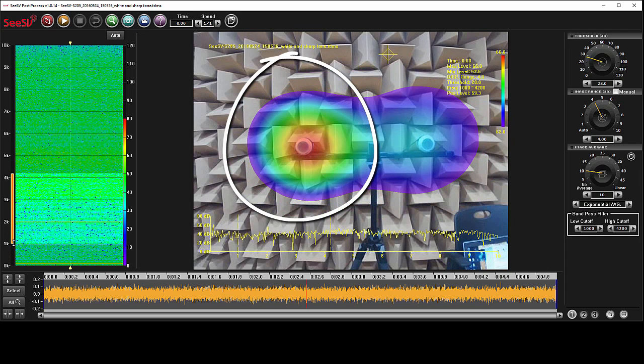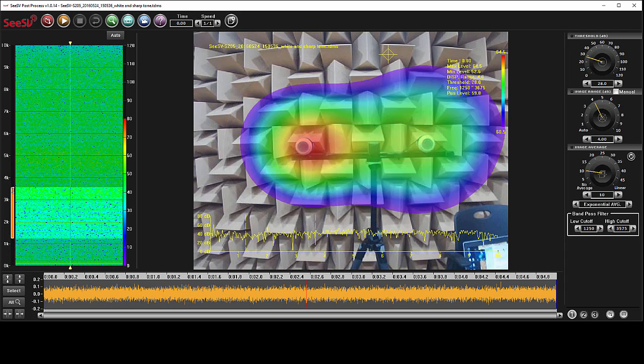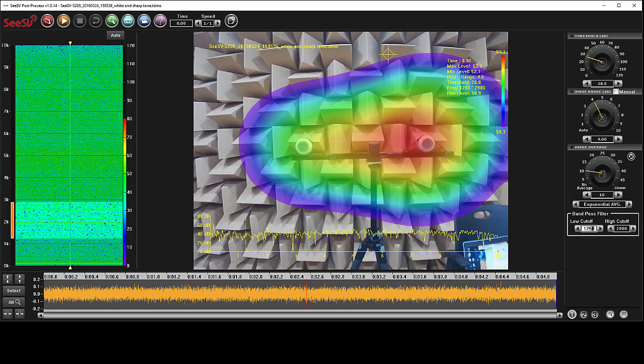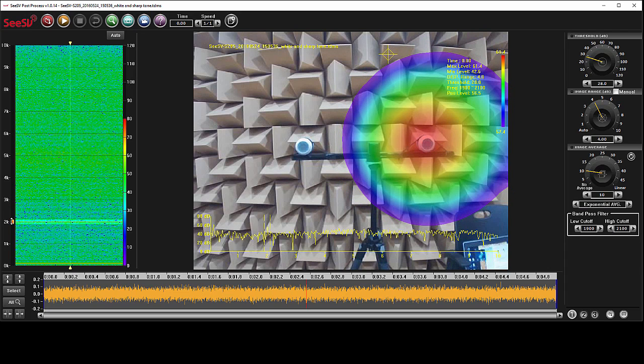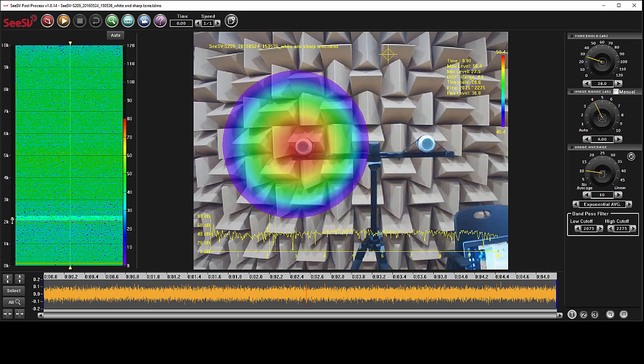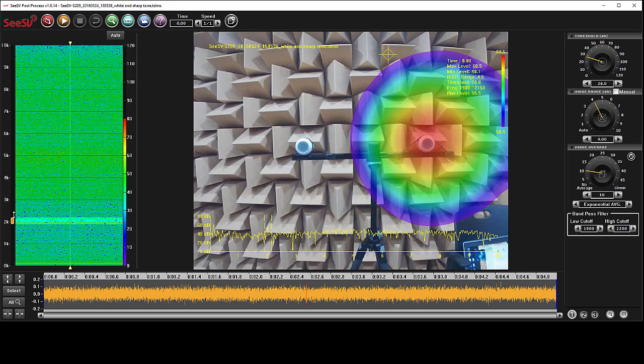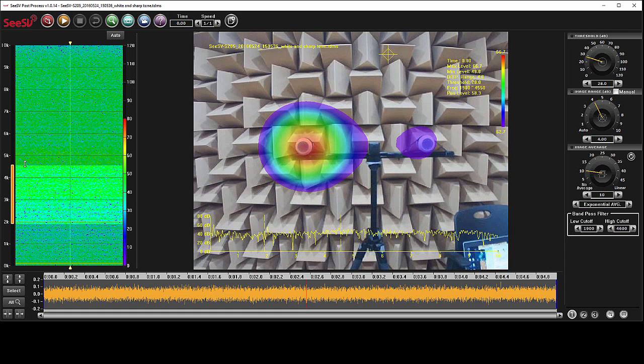But if you change the bandpass filter to focus on 2 kHz bands like 1900 Hz to 2100 Hz, you can see the beam power value on the right source becomes more dominant. As a result, in case of multiple sources, it is important to set the settings on the appropriate value in order to locate and recognize the noise source.